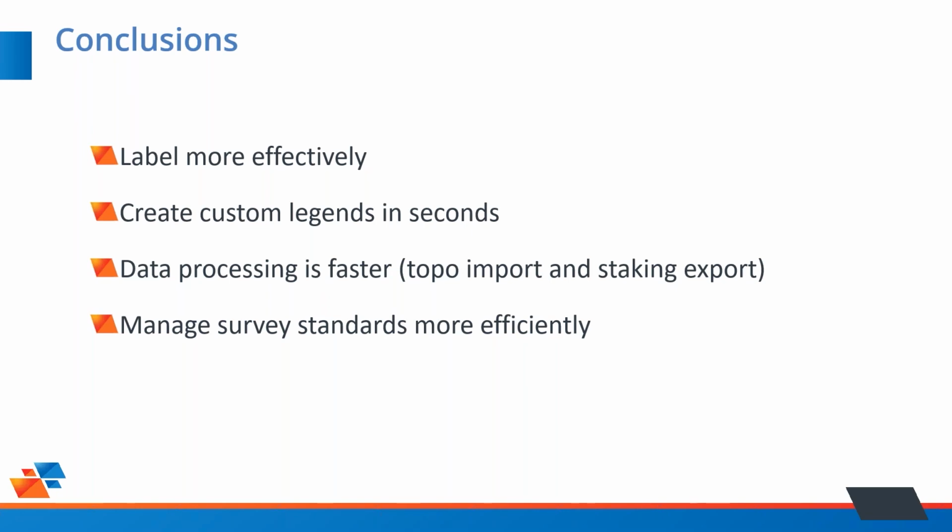And we decided to stick with model space because it's the way that Autodesk and AutoCAD is built to use. If it's Civil 3D labeling, obviously all of that has to be in model space. If it's annotative MText or MLeaders, that stuff has to be in model space to work correctly. And so everything is labeled in model space. And so with that, that's the workflow we got in line with.